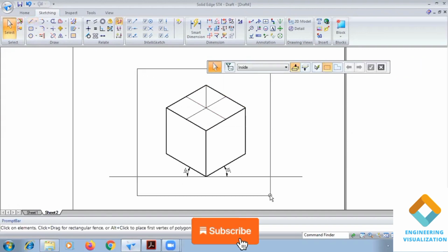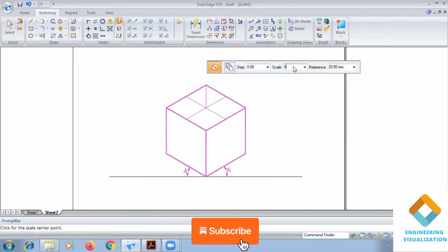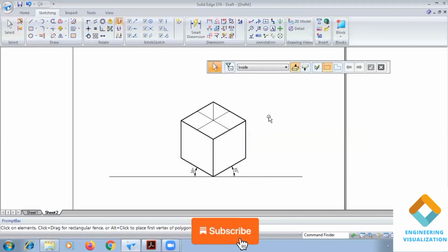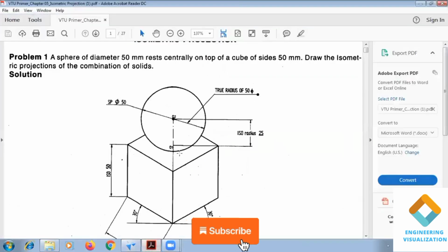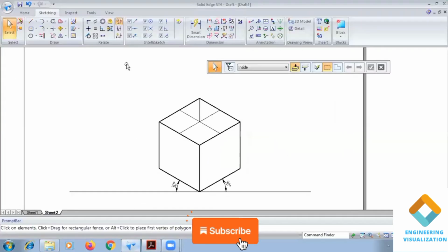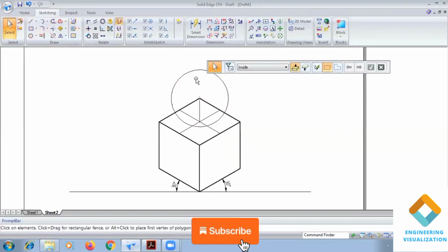Okay, so this step you remember, guys. Go to scale here, type here 0.816 or 0.823, you can type it. Okay, now go to circle and draw here. That's the center of the sphere. Now go to circle and draw a circle of diameter 50. Enter. So that completes the sphere here.